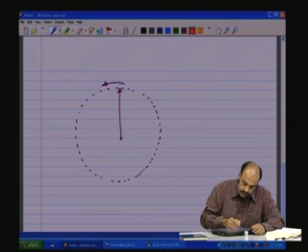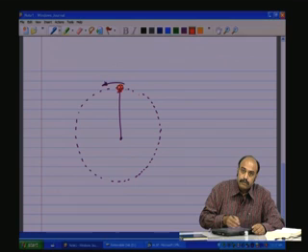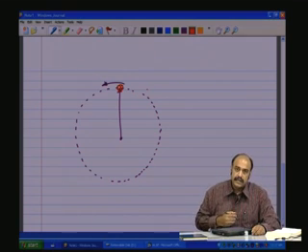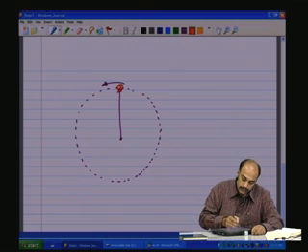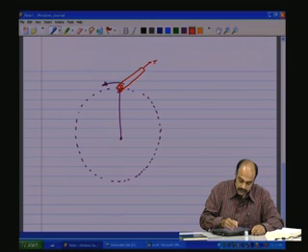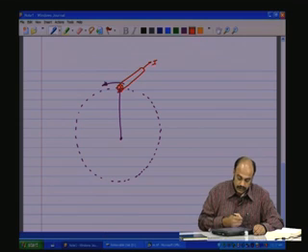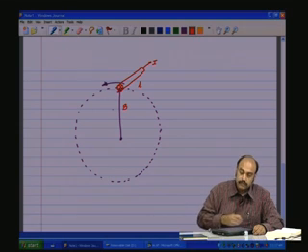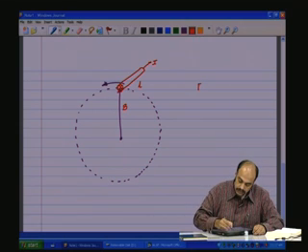and if we have a rotor conductor, this magnetic field which is rotating is cutting this rotor conductor, and as this is cutting the rotor conductor, there is a current which is going to flow through the rotor conductor, and that is I. There is a length of the conductor L. This magnetic field is of intensity B. So by the Lorentz law, you have a force which is BIL